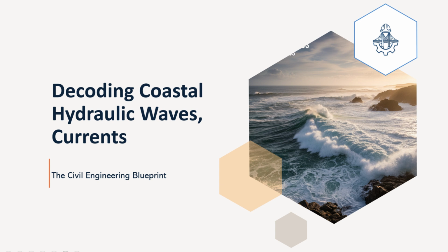So it really comes back to those seabed velocities we calculated earlier using linear wave theory, interacting with that critical threshold velocity for sediment movement, VC, that determine if erosion or accretion happens in the cross-shore direction as well. Exactly. When the instantaneous wave-induced velocities near the seabed exceed that critical threshold, VC, which depends on the sediment size and density, sediment grains begin to move.